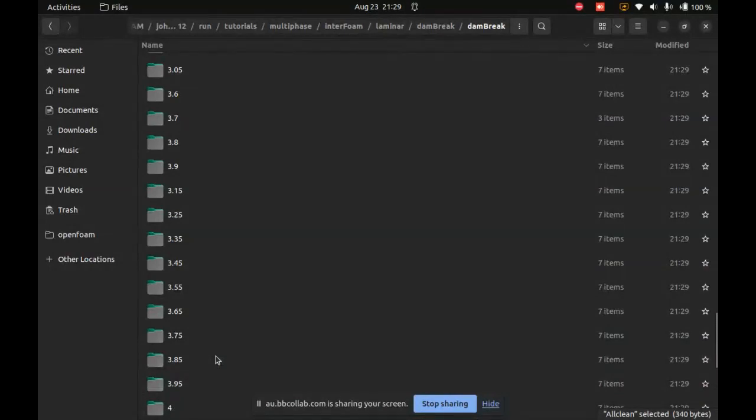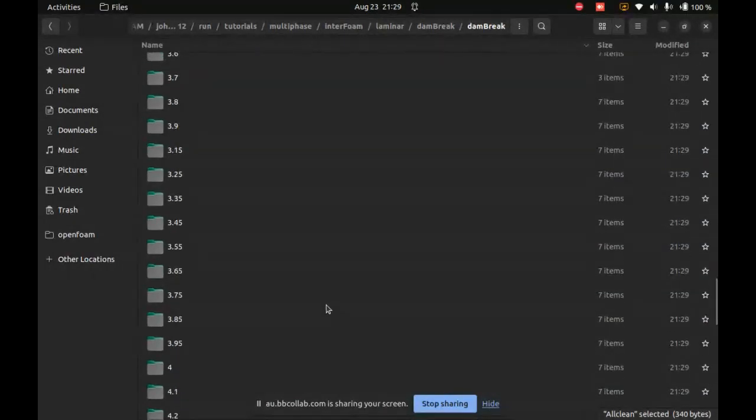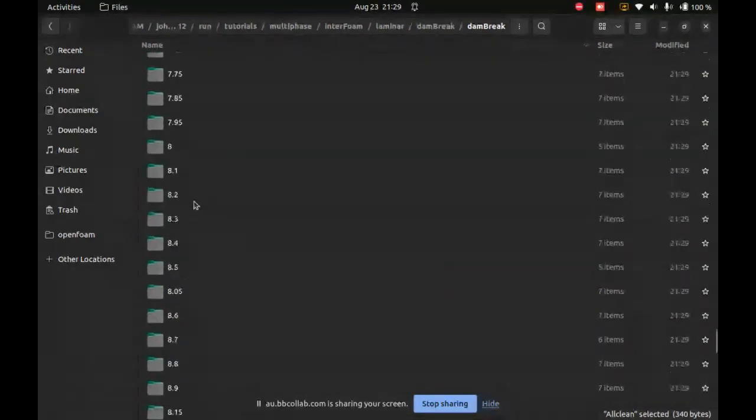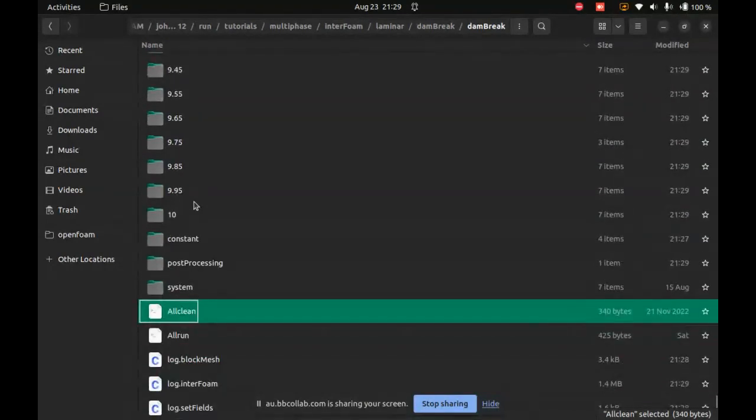So as you can see, this is one of the problems in OpenFOAM: if you specify too many time steps and you specify your write out time too often, you very, very rapidly fill up your hard drive. And that might not seem like a big deal, but trust me, it's a big deal, especially when you are solving nuclear boiling and you want to simulate a second, and you're outputting every 0.5 milliseconds. So yeah. All right.